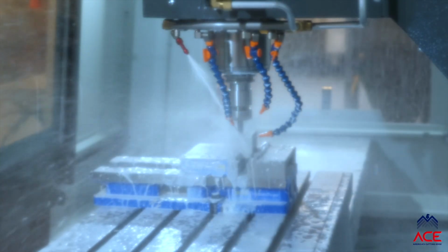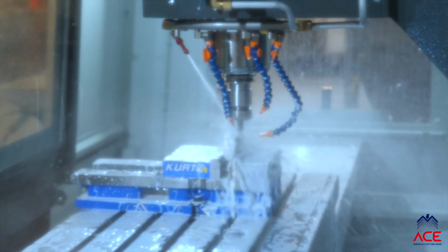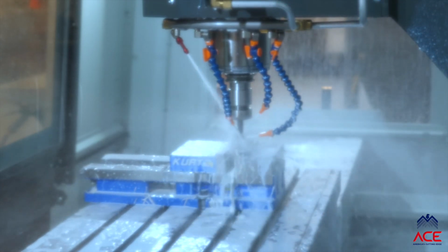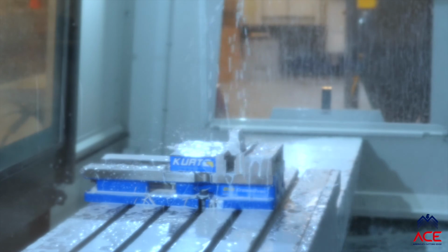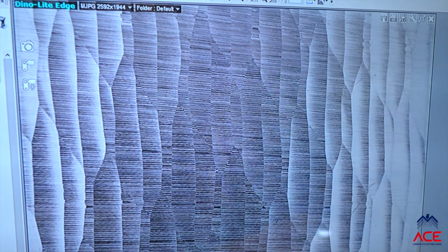We then completed machining tests to show stable and unstable or chatter. For those work pieces under the chatter and the stable conditions, we then looked at those surfaces. And we saw the chatter had a rough and irregular surface, and the stable machining conditions gave us a smooth surface with a regular pattern.